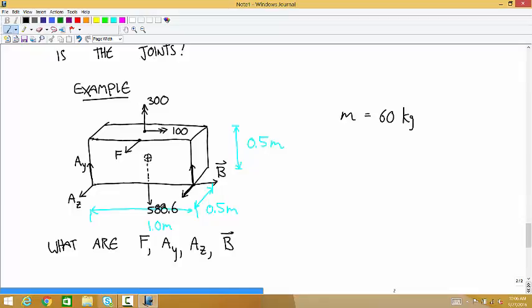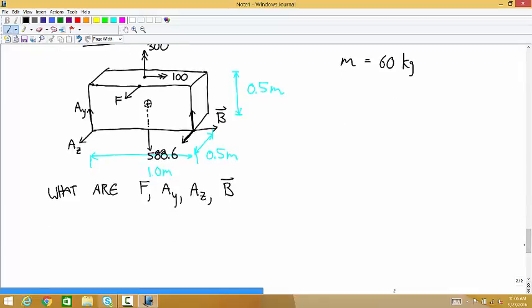So first, just thinking about the number of variables and the number of equations, do we expect that we should be able to solve this? Yeah, because we have 6 variables. We know we're going to get 6 equations. It doesn't always work out because some could end up being redundant or whatever, but it looks good at this point. So let's start filling out the table. As an about point, let's choose this, because it's where we have the most unknown forces.